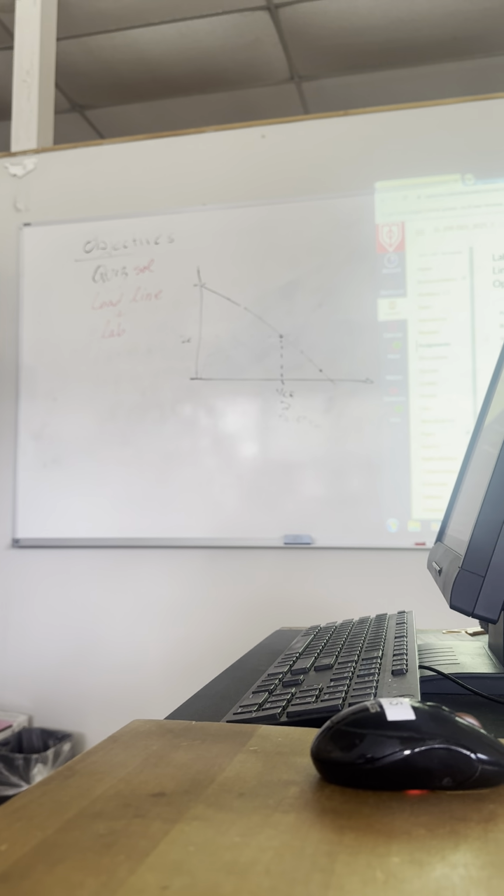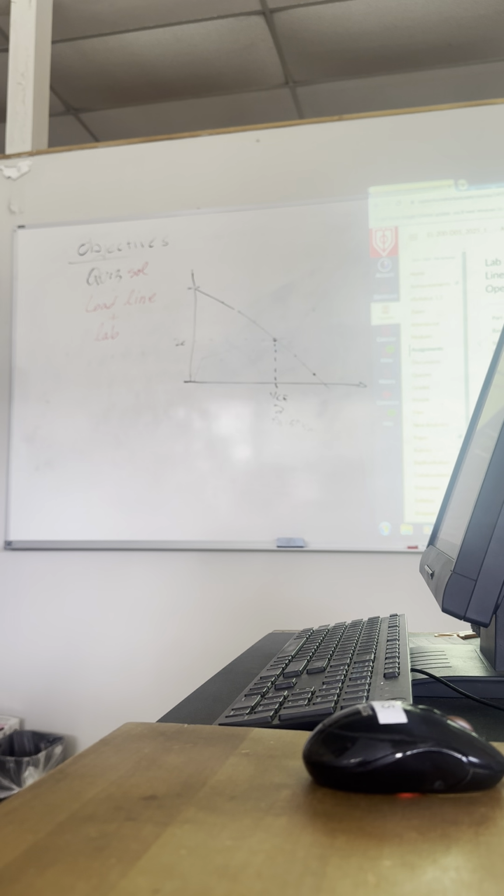So I know my cutoff and saturation point. No matter what, I'm going to be between these 2 points. Does that make sense? So I am controlling this circuit with IB by changing RB, and I'm moving the point across the load line. Now what if I wanted the load line somewhere else? Change RC. Does that make sense? With the same power supply, either you move it this way or that way.